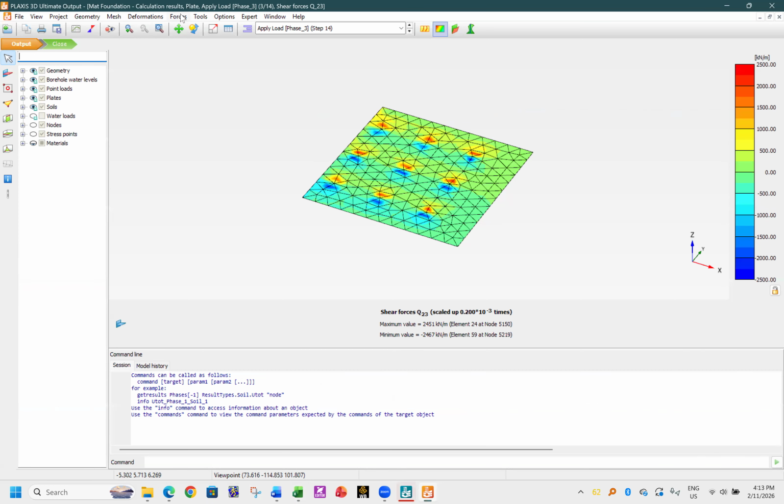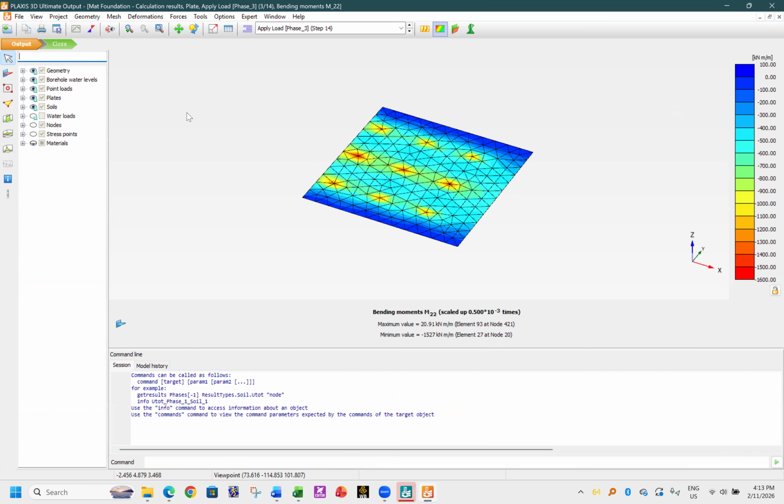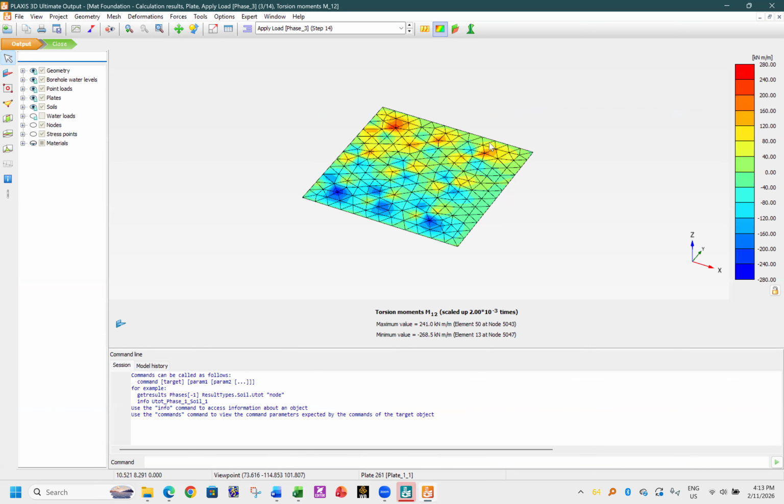And then bending moment, at 1527, there will be other things also. We actually get arbitrary values. So you put there and then you can get the reinforcement in both directions. Okay, understood? You can fix the thickness. You first place one thickness in Plaxis, and from there you get the values, and then later from moment and shear force, you can fix the thickness and then the reinforcement of the raft.